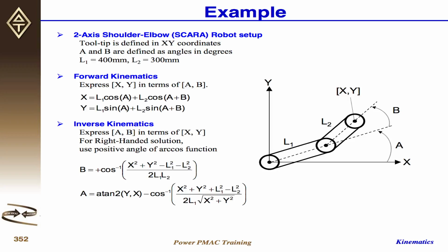And in forward kinematics, the input is the motor position, right? Here, we are using angle because this is one motor, and this is the other motor. The motor rotation angle counts can be represented as an angle. So there's another relationship between this angle and the motor counts, which is linear.